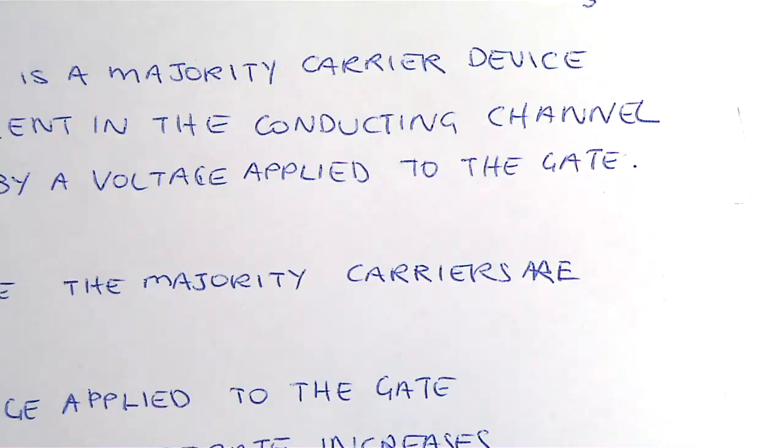So if we're looking at a 1 gigahertz signal of pulses, the spectral content of that is really in the many gigahertz. That's the only thing I'm trying to emphasize: if you're looking at, say, 1 or 10 gigahertz digital, you've got to be doing the design as if you were doing your analog design at, say, 50 gigahertz. You've got to be looking at the third harmonic, and that's something you need to always be aware of.